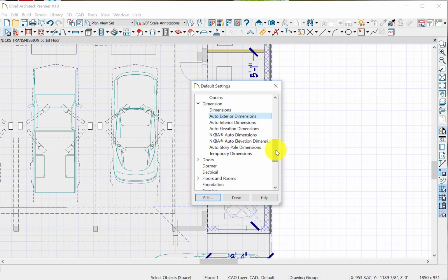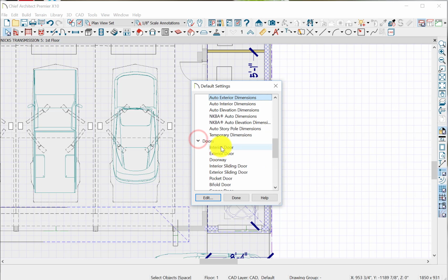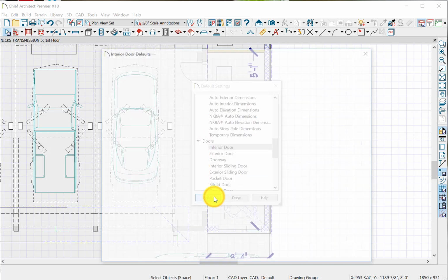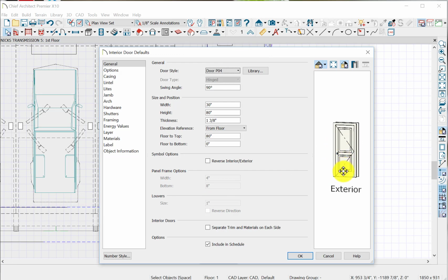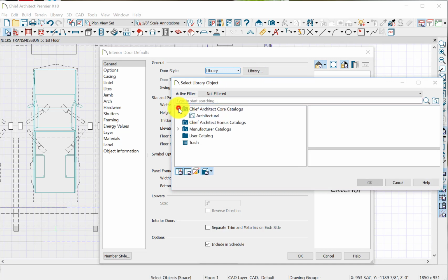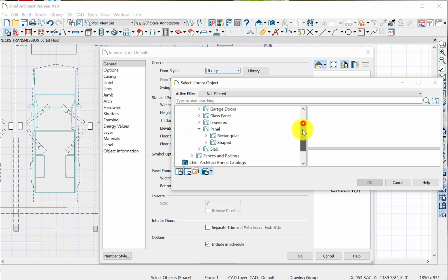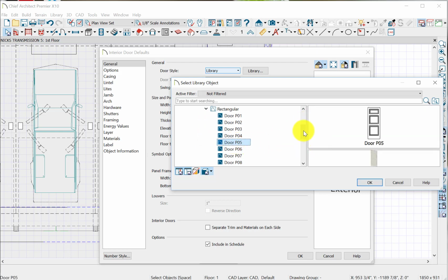It's fine. Doors, again, just like the cabinets. You can set your default interior door, exterior door. This one is set for this 2-panel style, but you can change it to slab style as your default door. So before you start the project, if you know the customer wants a special door, say they like the 5-panel door, you can go to your catalogs and pick a door. They like a 5-panel door. Let's say, old-fashioned 5-panel doors. I think is it this one? All right, this one.